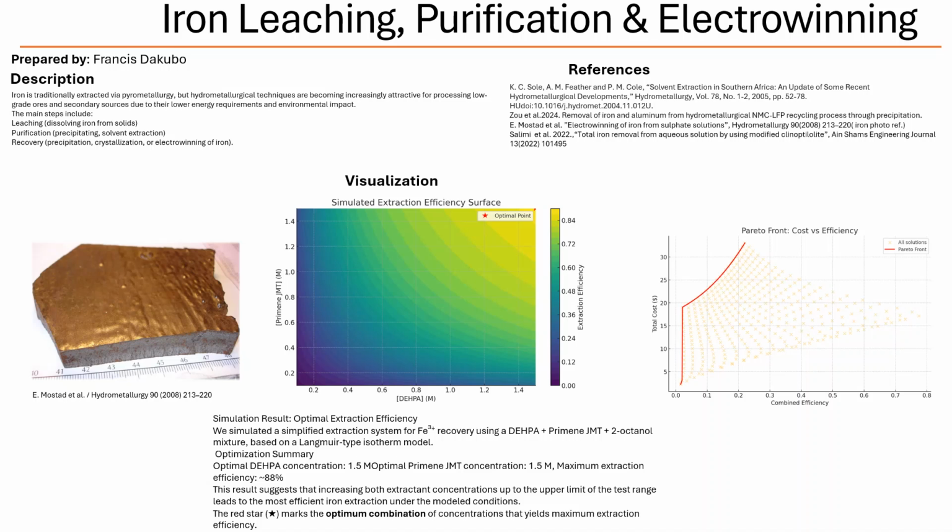Absolutely. Now, the goethite process, we talked about that in detail already, so let's move on to hematite. This is where you precipitate iron as Fe2O3, essentially rust, at even higher temperatures and pressures. You need an autoclave, a specialized pressure vessel, to do this. So hematite, high temperature, high pressure, sounds intense. It is. You're operating above 185 degrees Celsius and at pressures above 5 bar.